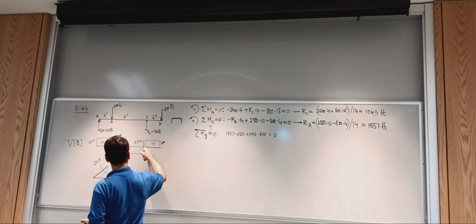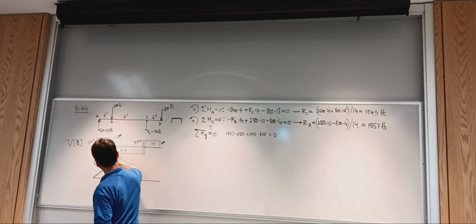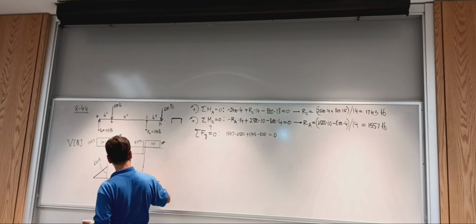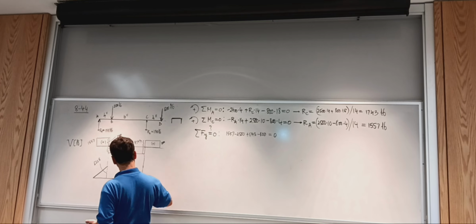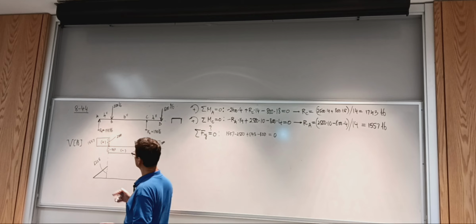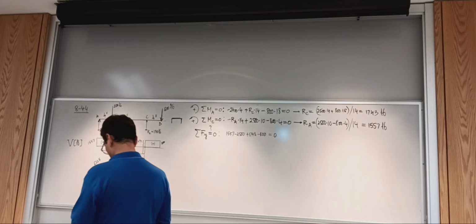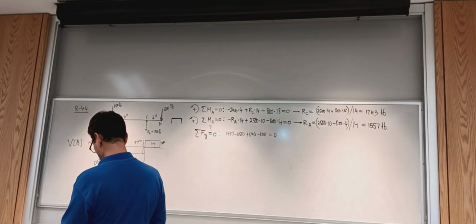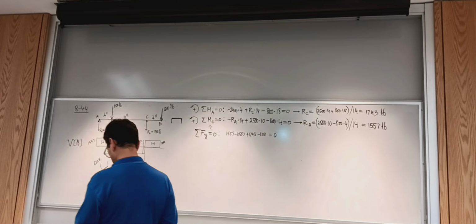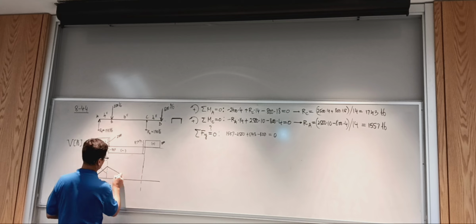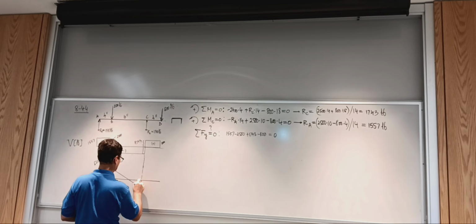So let's see, you'd expect the moment diagram to go below the x-axis. So we can tell the magnitude of M at point C by just subtracting or adding this negative area. So I have 6,228 on a calculator and subtract 943 times 10. That's negative 3,202. So this is negative 3,202.